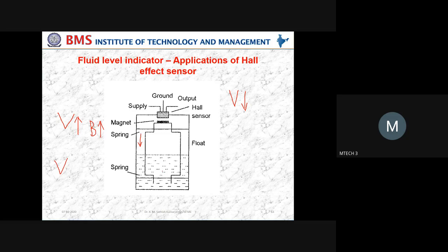When the distance between the magnet and the sensor is larger, the magnetic flux density is going to reduce. When there is a reduction of magnetic flux density, the value of voltage is going to be reduced. Now, the increase or decrease of voltage depends upon how close the magnet is to the sensor, which indicates whether the magnetic flux density is higher or lesser.